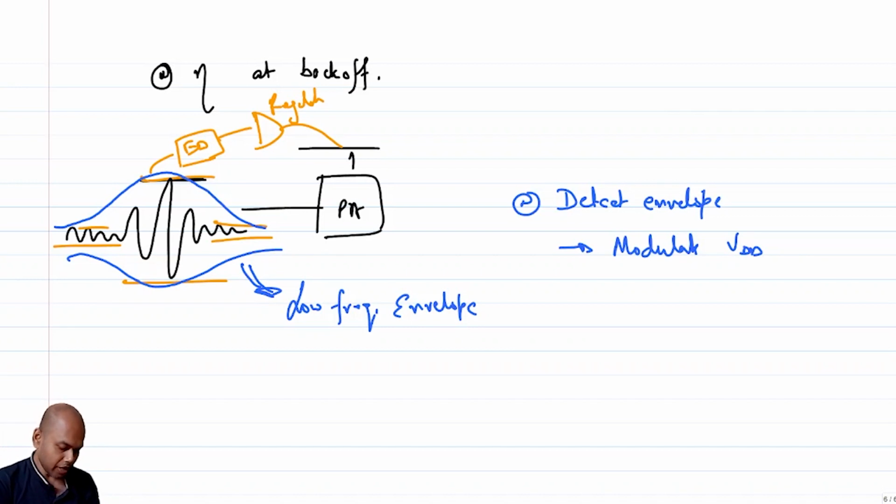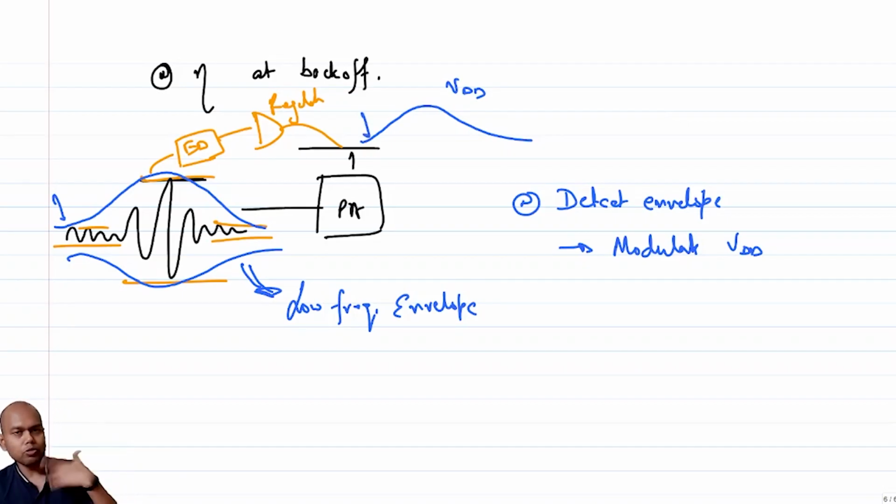So the VDD of the PA will also go like this. This is the VDD of the PA, which means that when the input is at low amplitude, the VDD will also come down so as to ensure that you are not unnecessarily burning a large amount of power. This is one way of increasing efficiency. Now, easier said than done, but you should appreciate that whatever extra circuitry you are putting, this is not supposed to work at RF. This is supposed to work at modulation frequency, right? Okay, so this is one way of increasing efficiency.